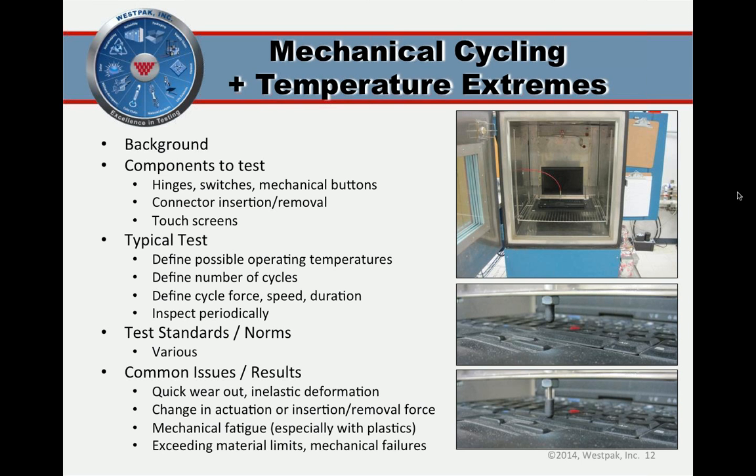So what we have pictured is a laptop in a small temperature humidity chamber. We have a single actuator set up to push the space bar, and you can see that in the bottom two pictures. This is just a demonstration, though. We could, with some machining, put an actuator over every key and button on the laptop and test them all in sequence or simultaneously as appropriate.